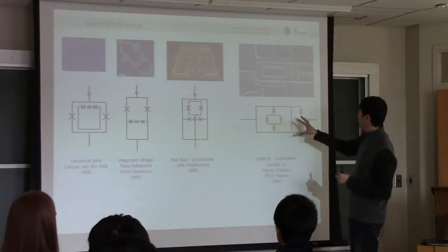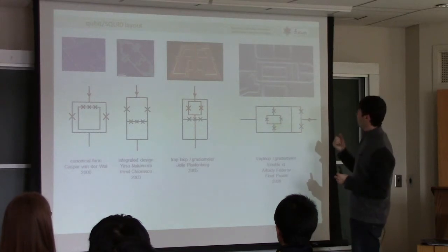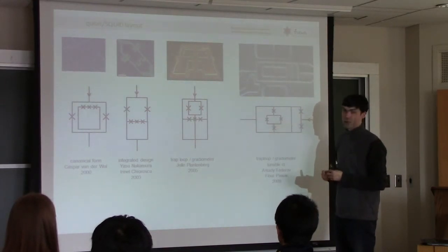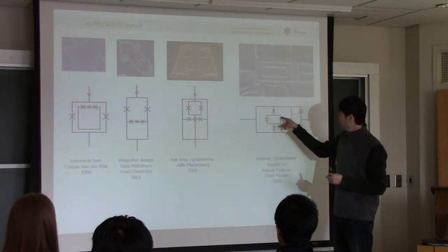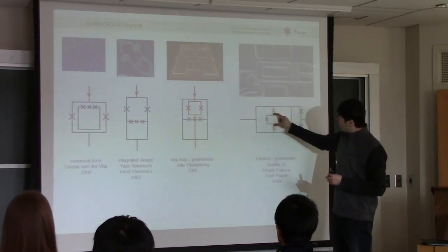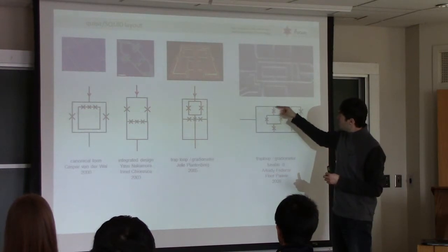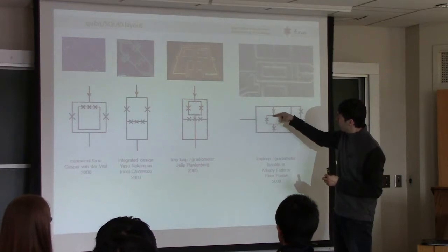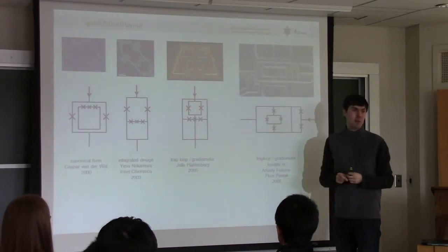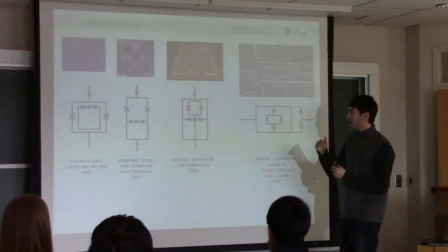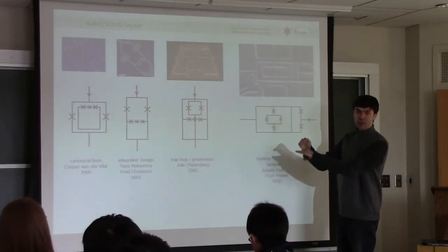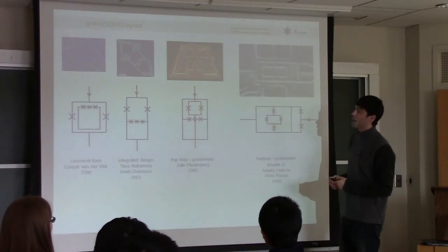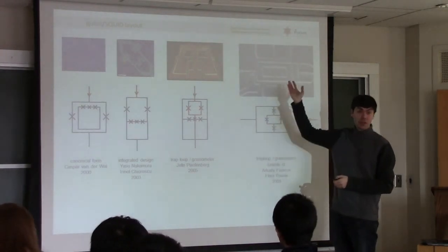And then finally, this circuit looks even more complicated, but what that allows them to do is to now tune the 3rd junction in the loop. Remember I told you if you have a squid, you can tune the Josephson energy between these 2 nodes. So they went for their qubit from 3 junctions to 4 junctions, and now applying a flux here, they can modulate the 3rd junction. And they can make the gap, the anti-crossing gap, tunable. So it's like an artificial atom, but you can completely rewrite it if you like.